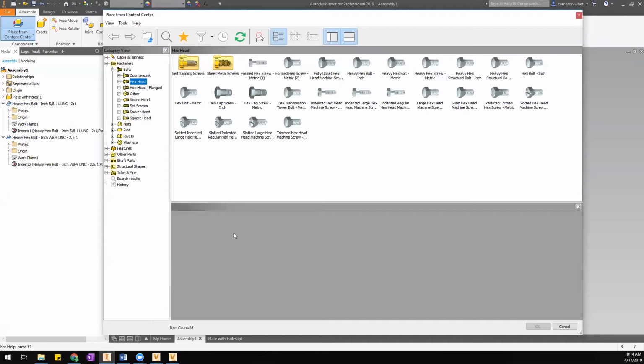All right, so one of the first things you'll want to do after you've assembled your team is figure out a naming convention for your families and your folders inside of the content center. Sorry, not folders, your categories. Yeah, define all that up front as much as you can, because that'll keep things consistent and organized in your content center. And it's also good because you're forcing people to name things in a specific way. It forces them, when they're creating new content, to think about things that they might not think about otherwise.